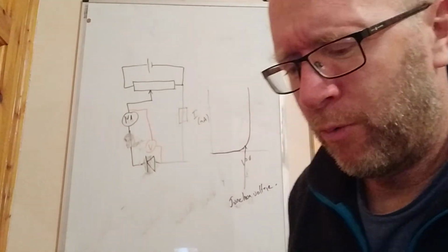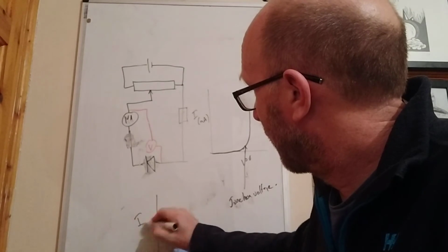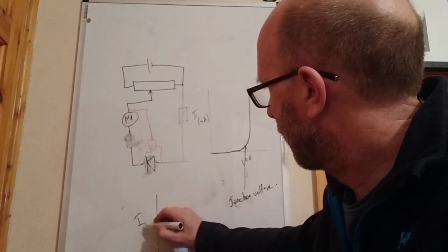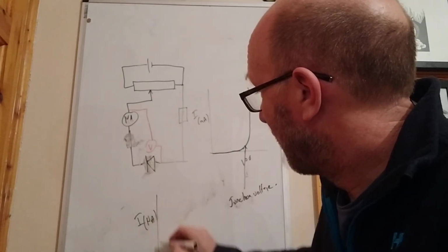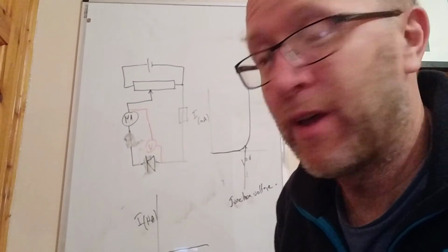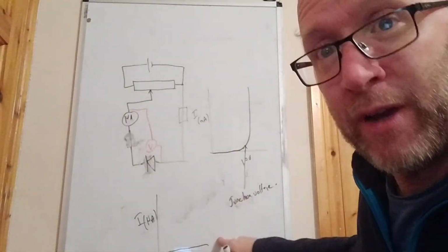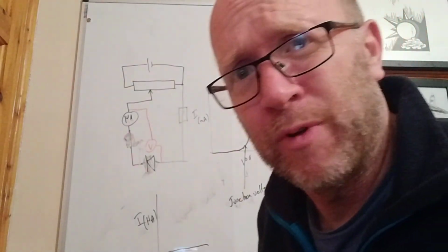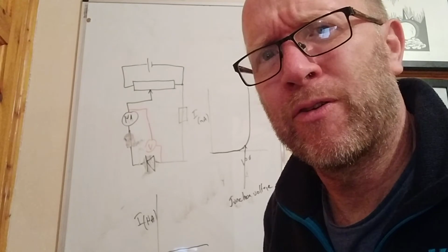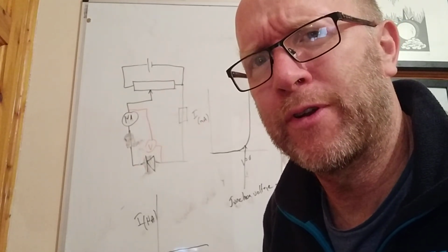Okay. Now, when we do that, this is reverse bias. We have current, we have voltage. The current is now in microamps, and effectively what you get is a very small current. Okay, it can break down, and you get a very large current, and then it goes back to a small current later. That won't be relevant, I wouldn't imagine, so don't worry about that. So that's it. That's your experiment IV graph for a diode.